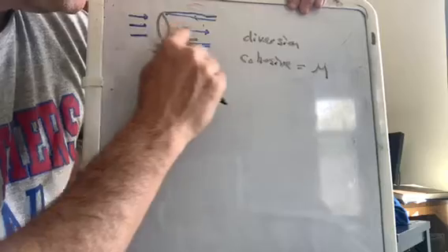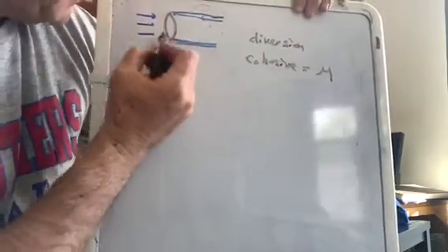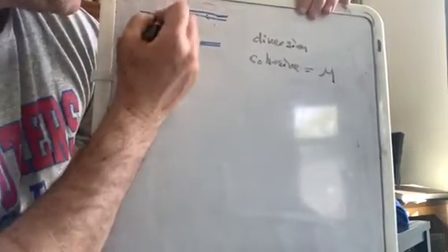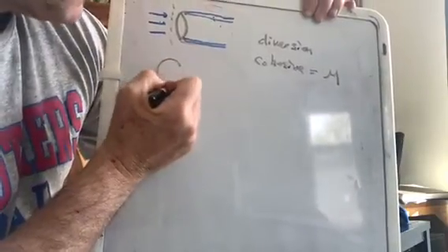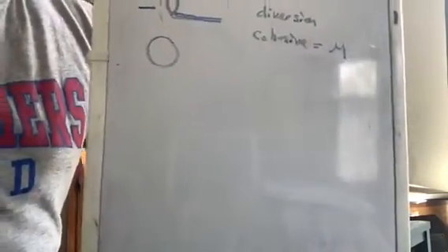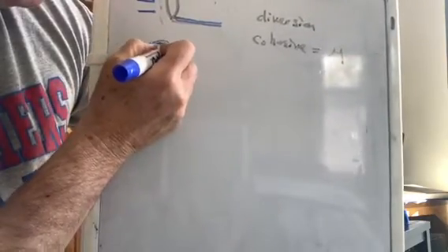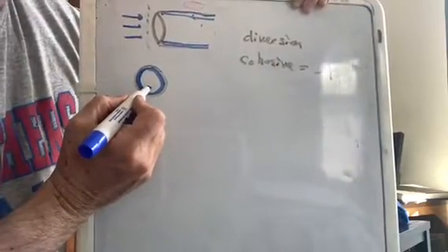It really comes from the fact that there is this no slip area. And if we have a certain flow rate coming to this point right here and then going into the pipe, it's almost like if you were looking straight on at the pipe, you could think about there being a little band around there that water has to get in and fit through. That water has to get through that band.